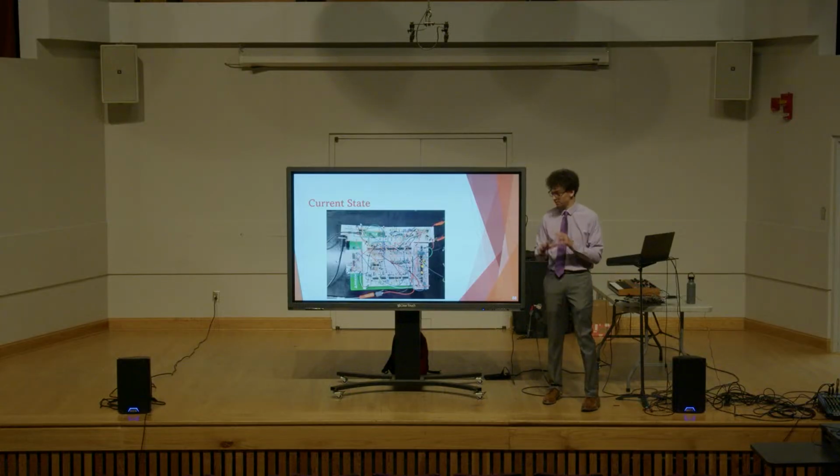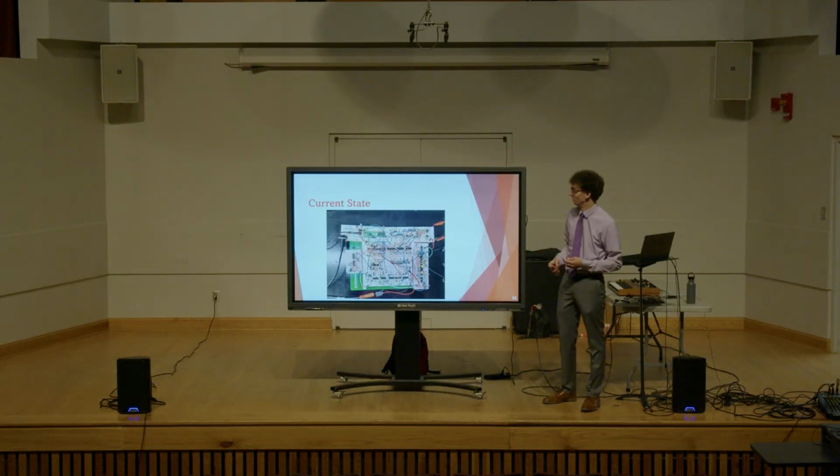So currently the circuit looks like this. I've just bumped up a bunch of breadboards. So the bottom breadboard of that group of 3 is an oscillator. The board up above it has a wave folder on it that is kind of working. Since it's not totally working, I did not take any audio samples of it. To the right of that wave folder are a bunch of current sources that convert control voltages to currents for OTAs. The board above that is the multiplexer circuit board, which takes the DAC output voltages and splits it out to a bunch of individual voltages, which you can see I'm passing around through this spaghetti of wires everywhere.